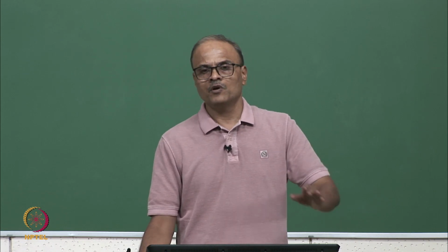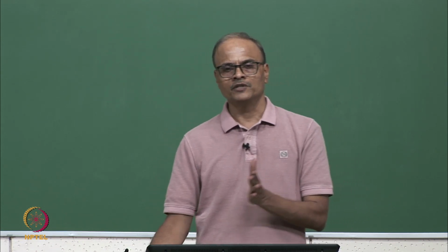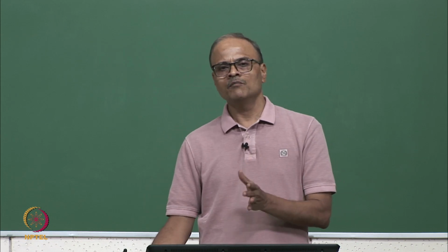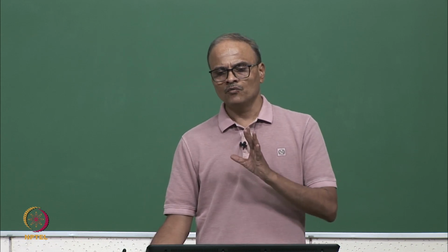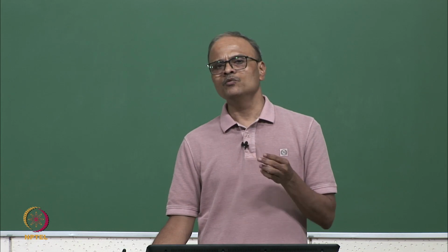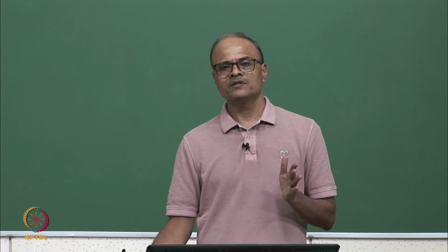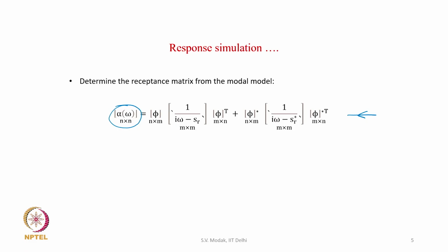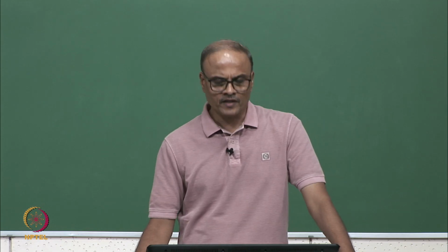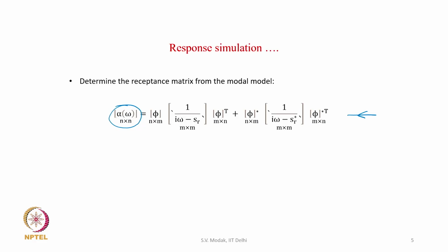There are n degrees of freedom where the measurements were taken, and n elements in the mode shape. So, now we can find the FRF between any two combinations of these degrees of freedom. That effectively gives us a receptance matrix of order n by n. This matrix can be used for determining the response to any forces acting on the system.